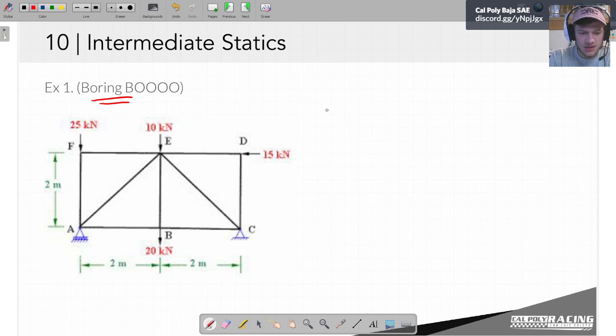So step one is do the external statics. We've got 3 forces here, 4 loads that are being put onto this structure. And then we have 2 places where we can have reactions. One here, and then one there in the horizontal direction, and not that one. Should be over here. This is the pinned joint.